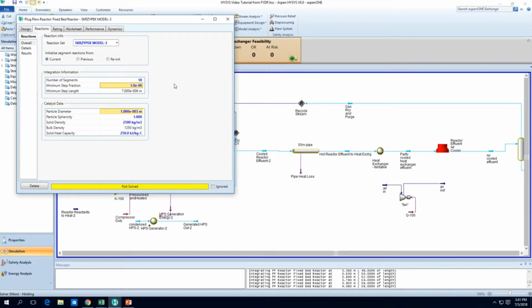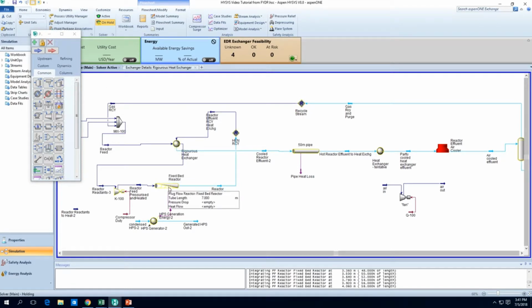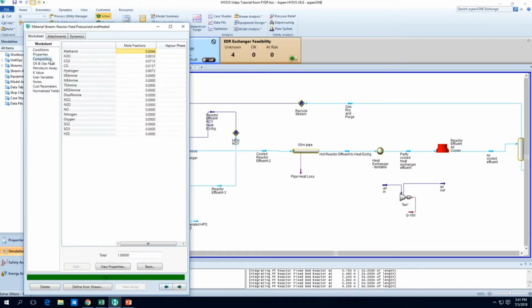And after we've converged the simulation the first time round, we can increase it back to 20 and then 50, so that the convergence is actually faster. So when you converge, these are some tips that can actually help you converge it faster. So you see HYSYS is going to run these iterations faster and faster. And you can see this actually building up.